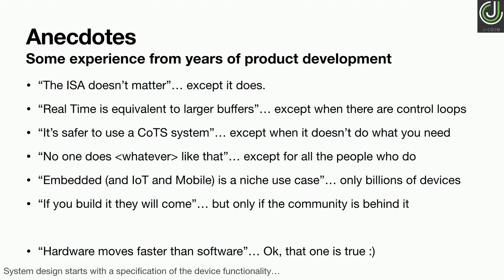So if you have, for instance, just a generic RISC architecture, what you find is that the memory bandwidth that the device needs in order to sustain the execution of the programs you're trying to run gets in the way of other things like sampled data, like DSP functions. And so the ISA that the J-Core offers is a compressed instruction set architecture that drives a standard RISC pipeline. It's really quite interesting when you look at what that does in terms of memory bandwidth and memory usage.